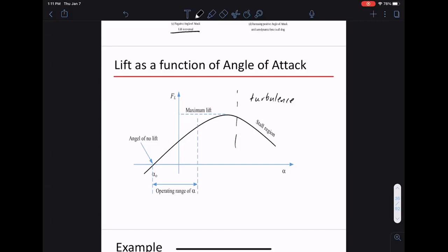It's a fairly complicated system to make work, especially for large blades, such as 8, 10 megawatt turbines, and there's a lot of machinery associated with it. A lot is to do with this sort of real-time control. And measuring wind speed is by no means trivial. It's not always easy to measure the exact direction of the wind coming in. So normally there is a safety margin.